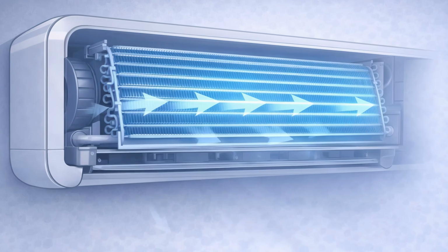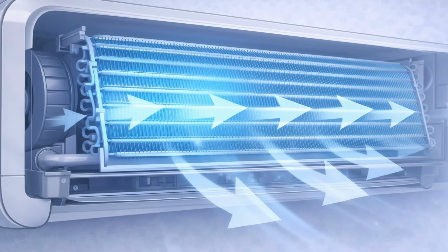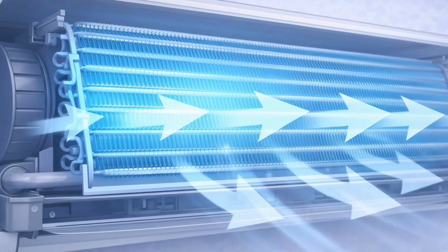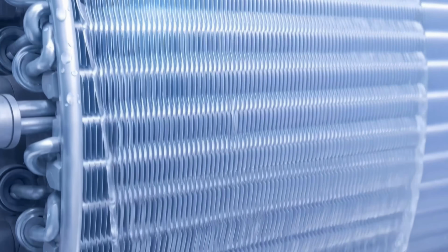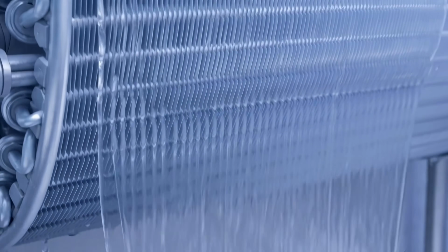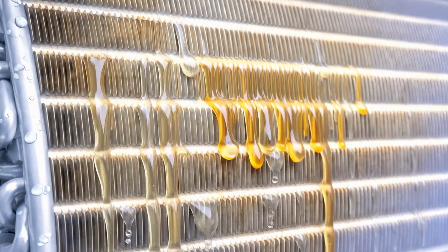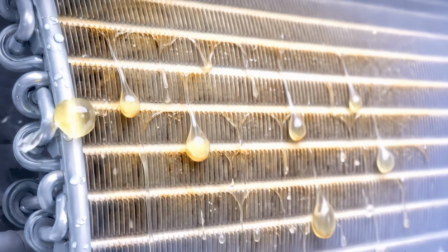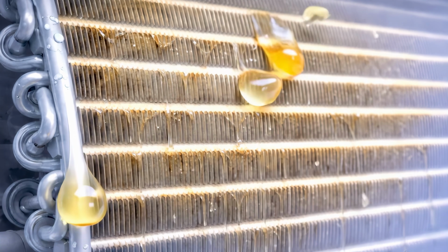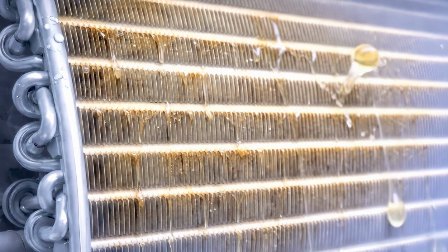There is another hidden cause that many people overlook: the cleanliness of the coils themselves. The evaporator coils are covered in thousands of tiny aluminum fins. These fins are designed with a specific surface tension to help water sheet downward into the drain pan. When the coils get covered in a light layer of oil, hairspray, or cooking grease, that surface tension changes. Instead of the water flowing smoothly down the fins, it begins to bridge across them or bounce off.